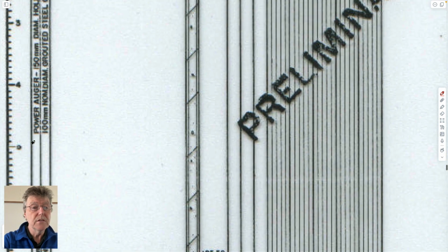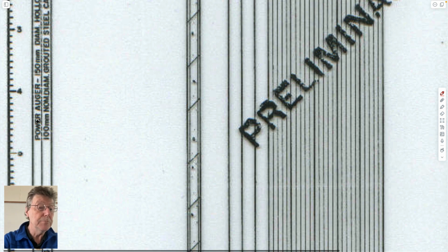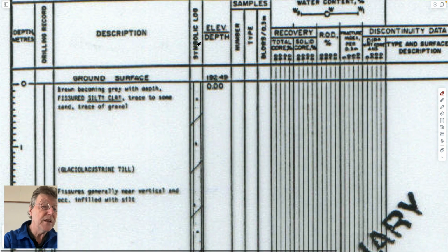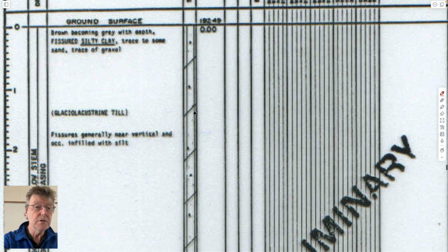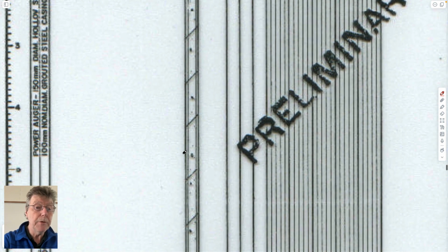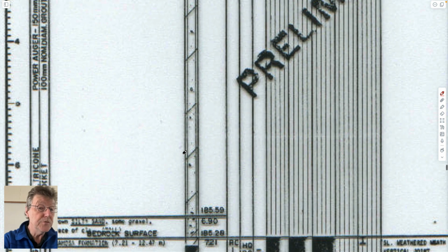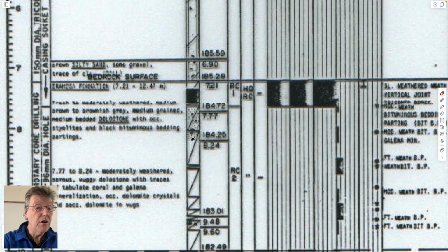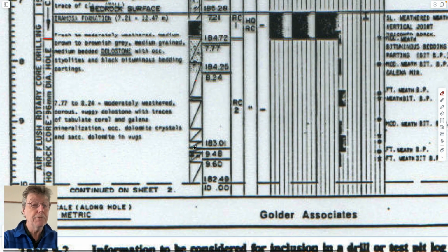So within the soil, on the auger, you'd be able to sample it, and you'd be able to sample on the flights. And so you'd mark in the actual symbolic log whatever you encountered, whether it was sand or silt or clay, and mark on the log exactly what it was. If you took samples by Shelby tube or by a split spoon, you'd mark those on there where you sampled. And then you'd also define what happens once you get into the rock. And in the rock, once you get below 7.5 meters, I guess in this case, not feet, you have a descriptive log of the core samples that you've taken by rotary coring. And so, pretty straightforward and rudimentary.